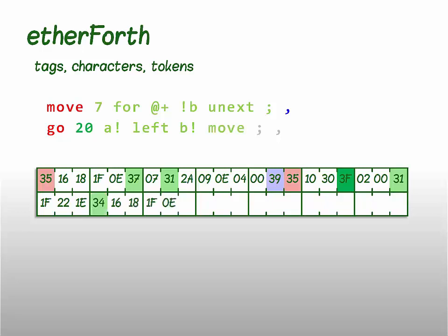Although green word move has the same color as preceding F18 instructions, we have to encode it with its own tag as a string of green characters. And since semicolon represents the return instruction, it has to be encoded as a green token. Finally, we add the end of line tag, and if this is the last line in the display buffer, there's always an end of block tag.